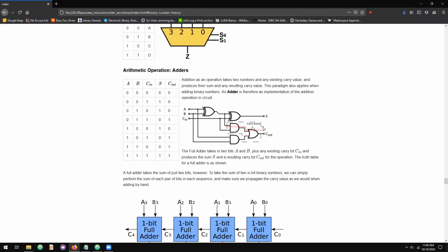You can also start building up arithmetic operations using digital logic gates. So what I've represented here is called a full adder. There is also a half adder, but I won't get into it because full adders are useful. An adder is a circuit representation that adds 2 bits together. And as we talked about with our binary number representations, adding includes using a carry value. So a full adder takes into account the 2-bit inputs, A and B, but also the carry value as input.